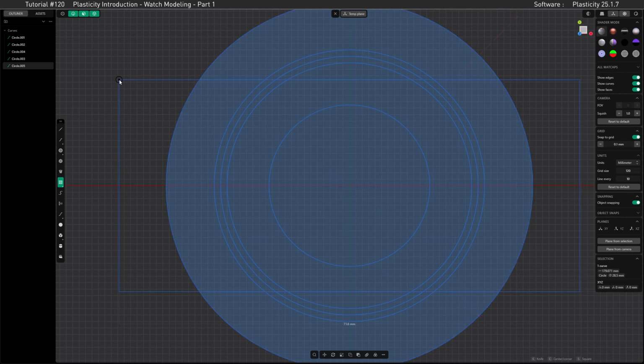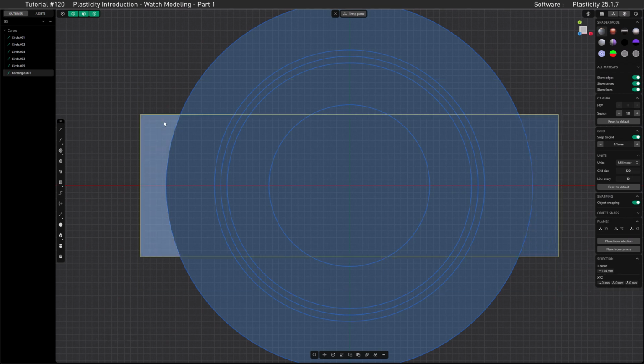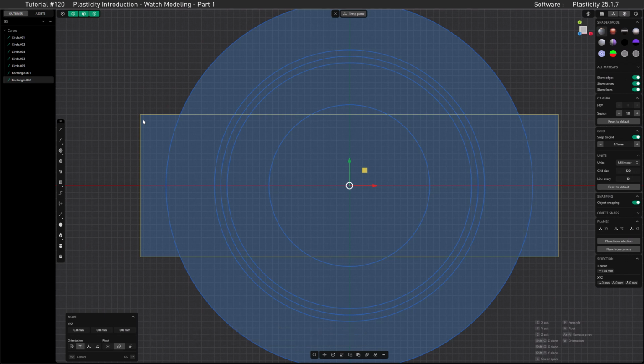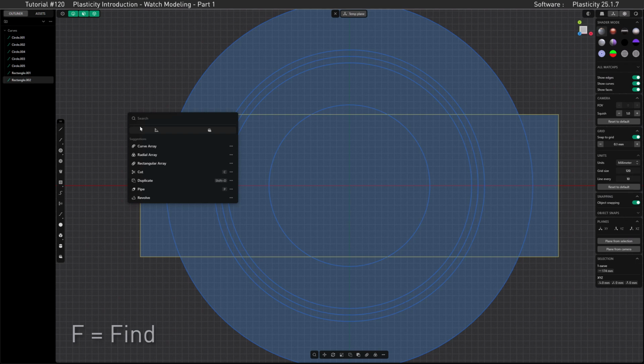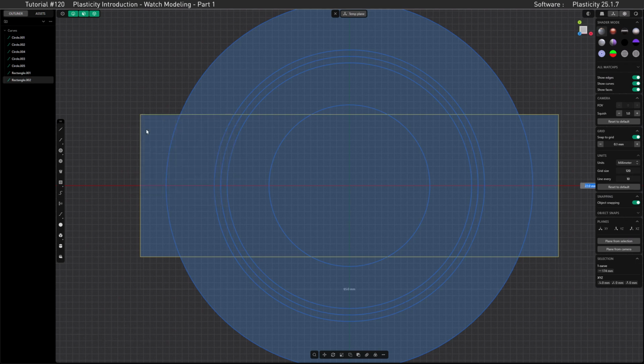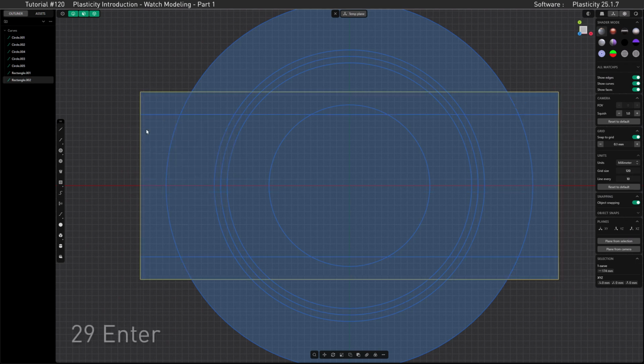Let's grow it out from the center, then hit Tab, 65, and since we have a dimension more, we hit Tab again, 22. Since we need 2 of those rectangles, let's duplicate it by Shift D, hit Enter, and then invoke the dimension command, so F, and we can go to the shortcut here, and instead of 22, we want to have 29. Here we go.